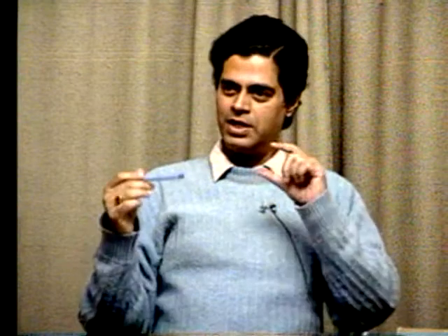Have you seen that isolation kind of things here? It is not shown. That P plus isolation, N-type epitaxial. Where is that epitaxial film gone? Is it necessary? Is it essential? No. Today, only in the very advanced CMOS technology, it has started using epitaxial film. But otherwise, there is no need.